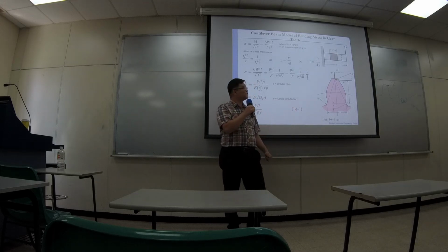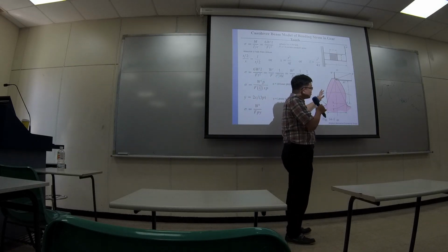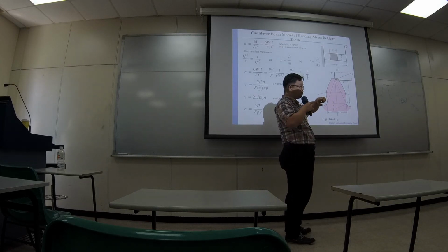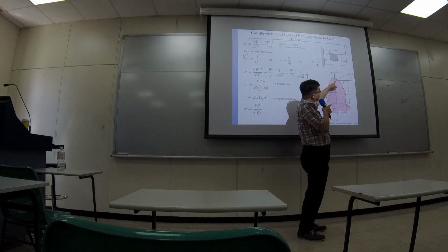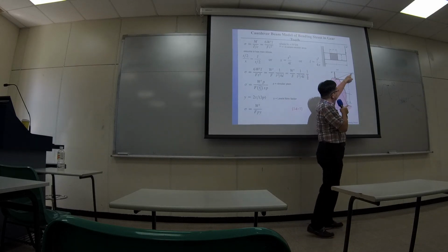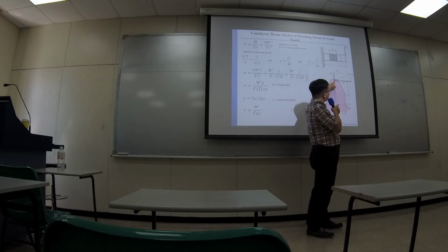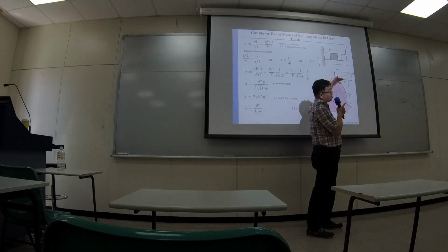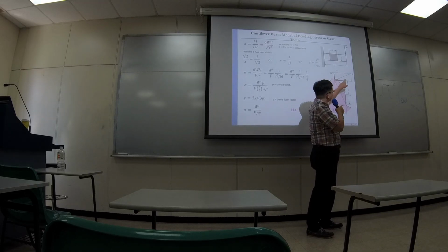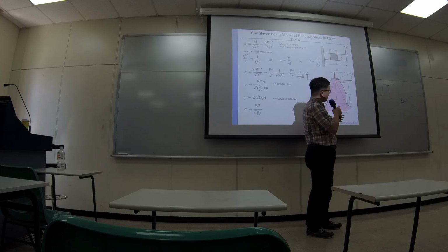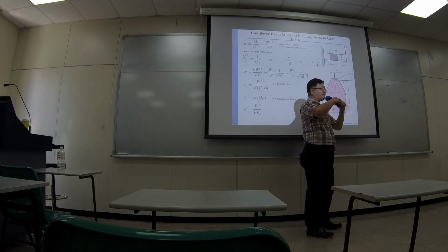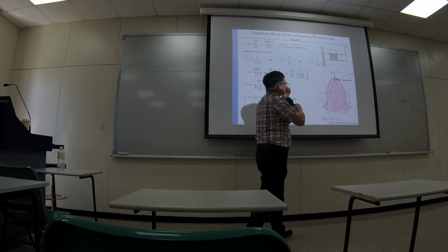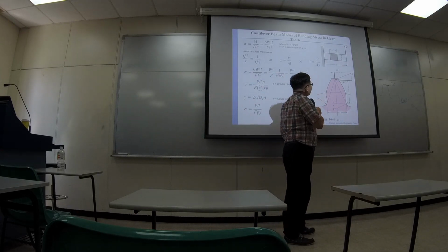This is why, okay? So there's one particular case where this tooth has conjugate connection with the other tooth, and the force comes at the tip. And there's going to be a force coming at an angle, and you have a transverse component and the radial component. We only care about the transverse one because that force is going to make this tooth behave like a cantilever, and it could break the tooth. So how do we study this?